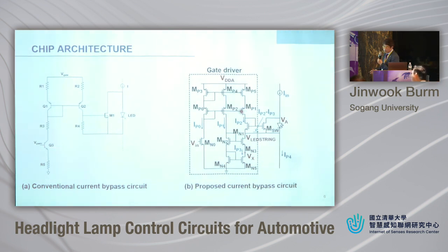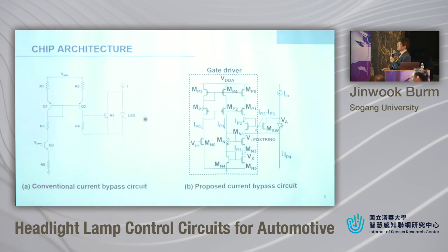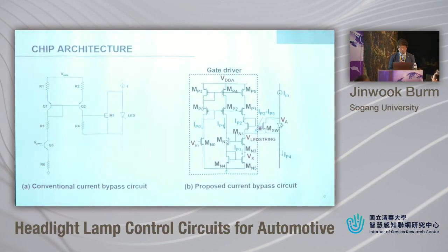this is a signal. The PWM signal is supplied to this transistor, and the current will flow through this R1. Since this is a current mirror, everybody is familiar with current mirror, the current will be copied to this R2 and Q2. By having some current flowing through Q2, there will be an IR drop that will turn this M1 transistor on. By having this M1 transistor on, there is a bias current to the LED. If this switch is on, this switch will deprive all the current from the LED. So if this transistor is on, then this LED will be off. By steering currents through this M1 and LED, we can control the LED lights. So this simple circuit can be implemented this way for our design.